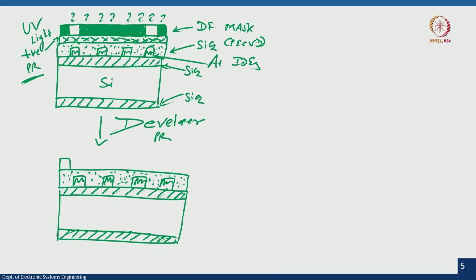So, I will have here, I will have here and I have here. What is this? This is the area of the photoresist which was not exposed. Since it was a positive photoresist, we will have the similar pattern like our mask, right. So, positive photoresist stays in the area which was not exposed. The area which was exposed to light, that particular photoresist becomes weaker and it gets developed in the photoresist developer. After this step, you know what to do, you have to perform the hard bake.